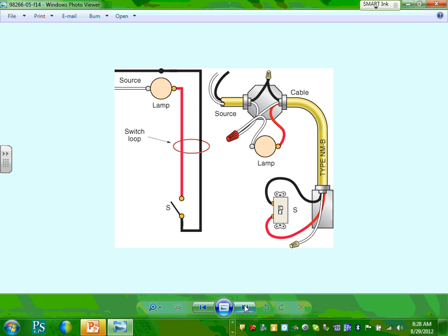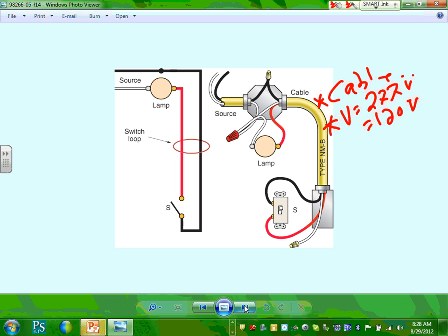If you are wiring with cable, NM cable, MC cable, AC cable, and this switch is controlling a light, not a garbage disposal, and the voltage for these, this has to be cables only, this rule applies. And number 2, the voltage has to be 277 or 120 volt. So Jamie means if you are wiring with 240, it doesn't apply. It has to be a grounded circuit, right? And what else did we say?